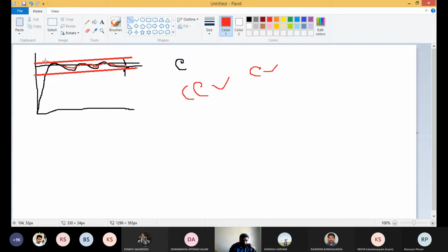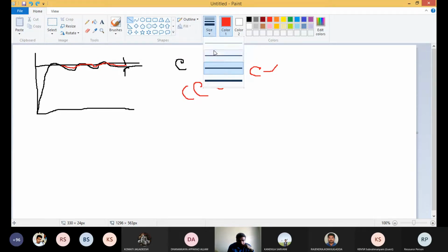That's how to derive the range of the error signal. By taking the range only, we are able to set the span of the membership functions. So by taking the time response and drawing the lines like this, and observing the deviation between the maximum value and the minimum value, we take it as the range of the error signal.